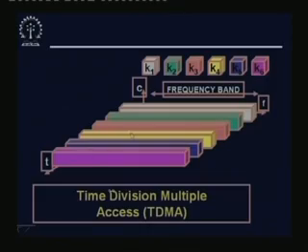So, this is the diagram for the time division multiple access. The entire frequency band is given to one particular channel for a short amount of time. Then for the next short amount of time another channel gets the entire frequency band and so on. As it is there in standard time division multiplexing, the same thing applies.